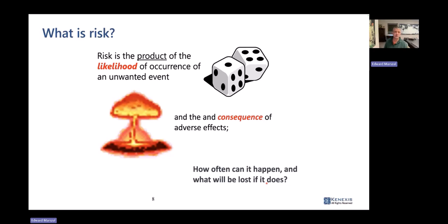So as we're doing this risk analysis, or as we're selecting the SIL target, we are doing it based on risk. And that was done very specifically, very deliberately for originally the ISA Standards Committee, and now it's moved out to a larger group of people in the IEC committee. And that's because we didn't want to prescribe what the design of a safety instrumented function looks like.